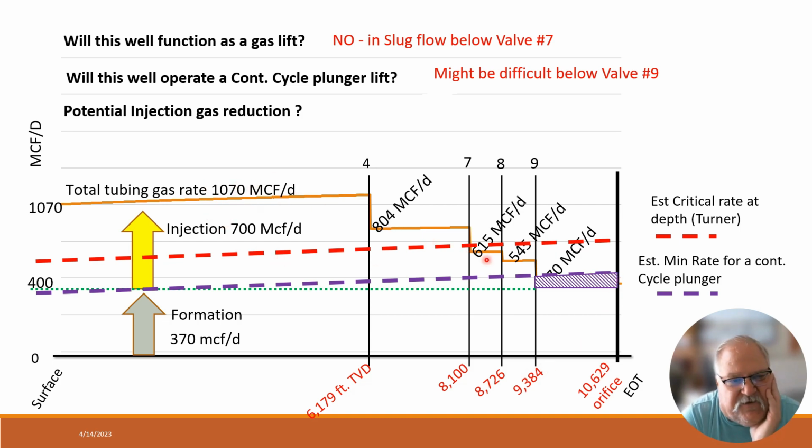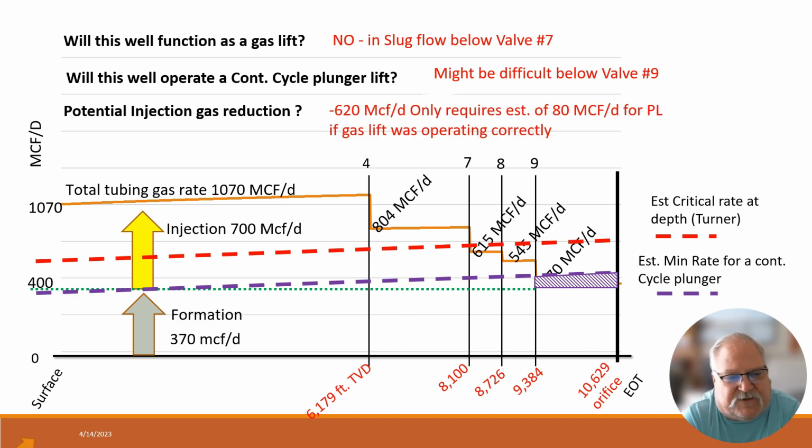So you can see how if we had a plunger in there, I could just keep cranking up that injection volume, but it would just push more up here. It wouldn't make that plunger move any faster from the orifice. It might speed up a little bit here, but chances are 90% of the extra gas you inject is just going to go through these top couple of points. It's not going to speed the plunger up until it gets past that point. Then it's going to come very, very fast to surface and really start pounding the heck out of everything, damaging springs and plungers and stuff like that.